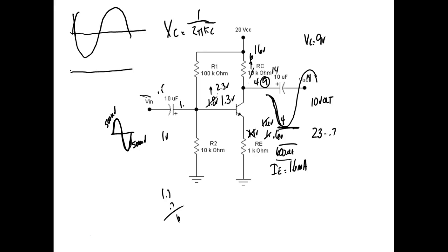What's about the lowest frequency that we can comprehend? Anybody know? Usually around 30 hertz. Usually people round off the top around 15 kilohertz. Most of your amplifiers are designed around that range. The upper end of the telephone system is like 3 kilohertz. It's very, very low. So using big capacitors in here, you're just wasting your money, because you wouldn't be able to hear the difference with your ears anyway, right?